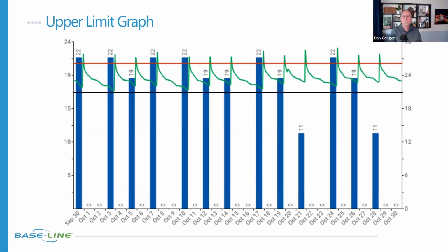And that will vary depending on the soil type. So in a sandier soil, it's going to see that application of water faster than if it were on a clay soil, where it would take potentially minutes to even hours for that application of water to infiltrate the soil profile, even a couple of inches.